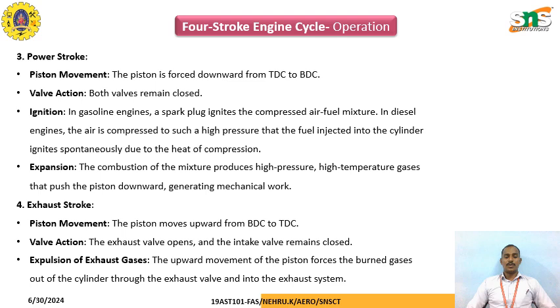The piston moves up from the bottom dead center to the top dead center. Valve action: exhaust valve opens and the intake valve remains closed. The upward movement of the piston forces the burnt gas out of the cylinder through the exhaust valve and into the exhaust system.